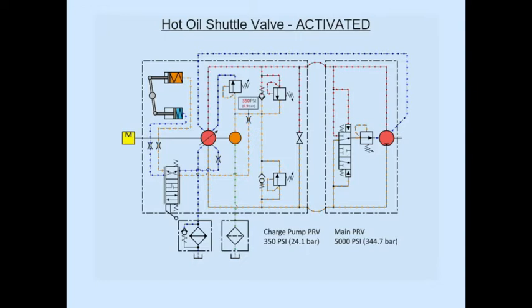If I put a new pump, a new motor, or a new pump and motor on the machine, my first responsibility is to make sure the charge pressure is set at charge pressure recommended by the manufacturer plus case pressure. Then I have to cycle forward and reverse and make sure on my charge pressure gauge I'm dropping 30 to 50 psi. And if it surges, in other words, if it goes down from 350 down to, let's say, 330 or 300 and comes back, it's not working. It's got to be a definitive drop from 350 to 300. Definitive drop.